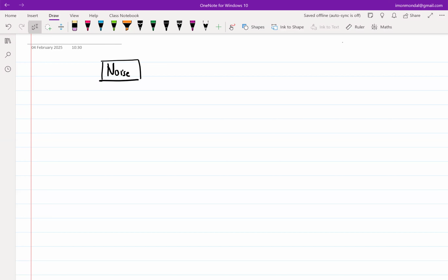But then we saw there are issues with that. The issue was basically that you have leakage through the capacitors of the mixer switches, which in effect comes back as input into the mixer switches and causes all sorts of distortion issues further down the signal chain. Also, the additional problem is that it goes through to the antenna at a fairly high power with respect to whatever you are receiving, and it can cause problems to the neighboring receivers. Right. So that was the big problem of 0 IF receivers.